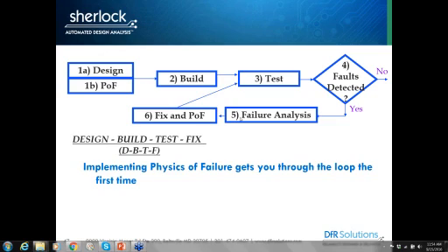Your printed circuit board is getting stiffer at the cold temperatures. Your solder joints are getting stiffer. And what we have seen during our testing is, because at cold temperatures the solder is very hard and your printed circuit boards are hard, for the same vibration input you're getting lower deflections, lower board level strains. At the cold temperatures, things last a lot longer. On the hot side your board is softer. You're getting larger deflections, more strain is going to the solder. Things fail very much sooner. So we do have the information. We are working on it. It really comes down to the GUI and how to structure that user interface.